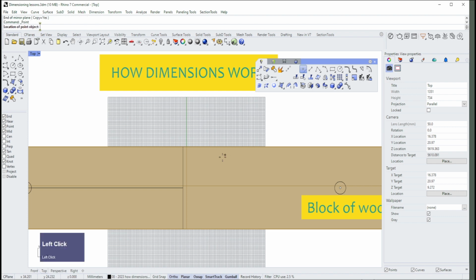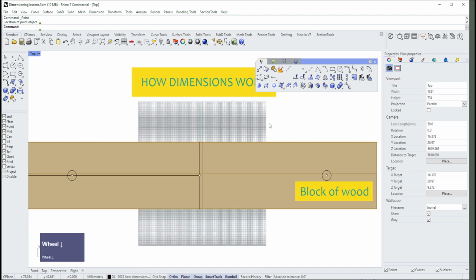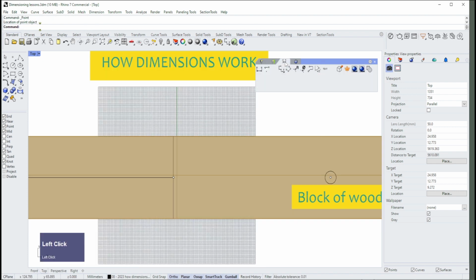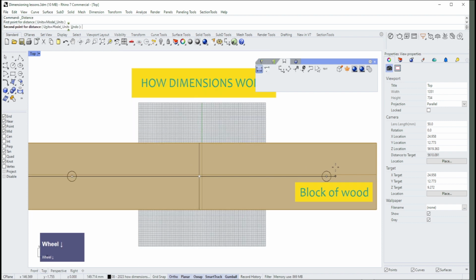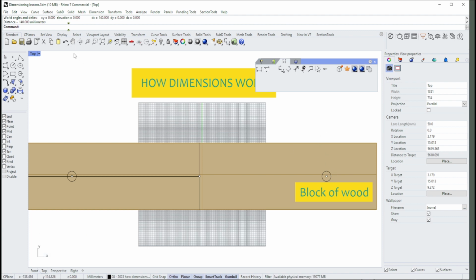Okay, so essentially what I would do is I would use that center line, get the center point, which would be a point that you'd actually mark. And then I would use my ruler with maybe a set square, just to measure what that is. That's 140. And I'd mark another point. Okay, and then I would be able to drill another hole.